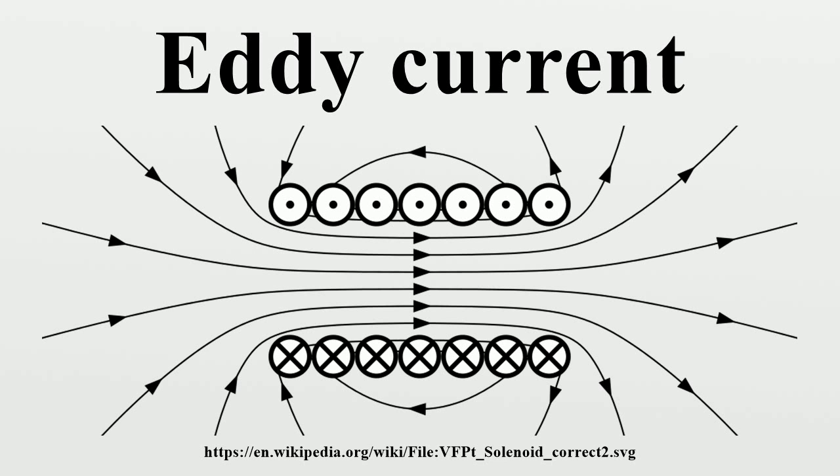Using electromagnets, as opposed to permanent magnets, the strength of the magnetic field can be adjusted and so the magnitude of braking effect changed. Repulsive effects and levitation. In a varying magnetic field, the induced currents exhibit diamagnetic-like repulsion effects. A conductive object will experience a repulsion force. This can lift objects against gravity, though with continual power input to replace the energy dissipated by the eddy currents.